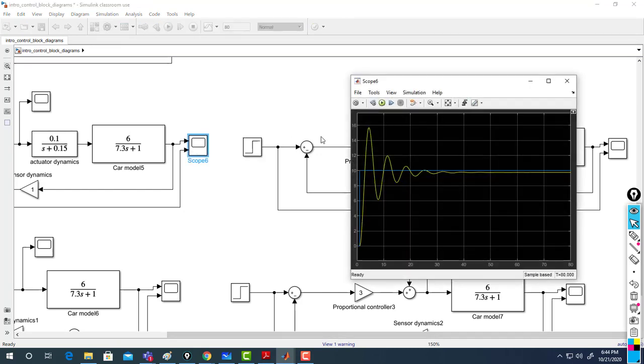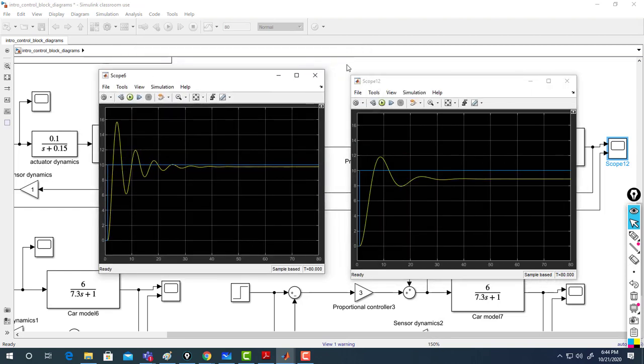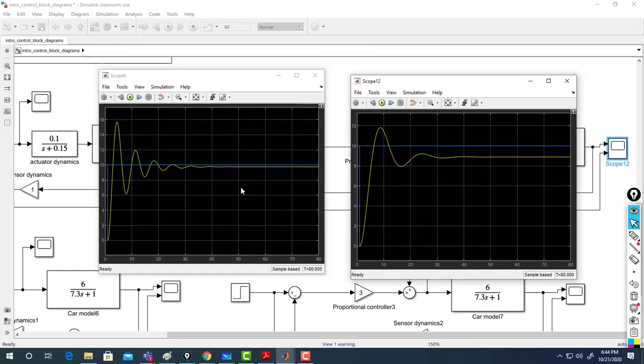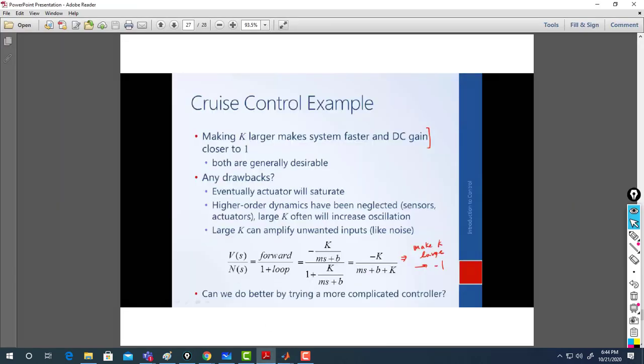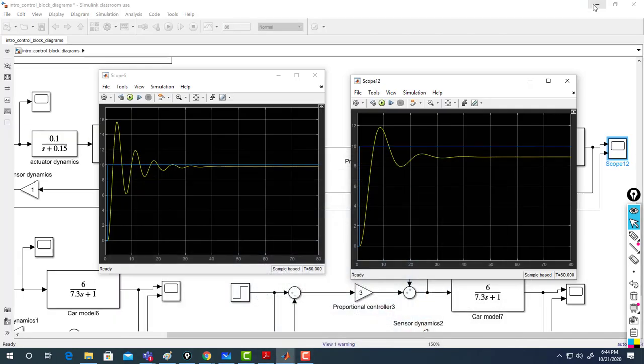So now let's look at both signals at the same time, so you can see the effect of increasing the proportional gain. This is a drawback. And this sums it up. Doctor, the system will always remain stable, it's impossible for it to become unstable, right, no matter how much we increase it? Yeah. It doesn't lead to an unstable system. It doesn't make your system unstable.